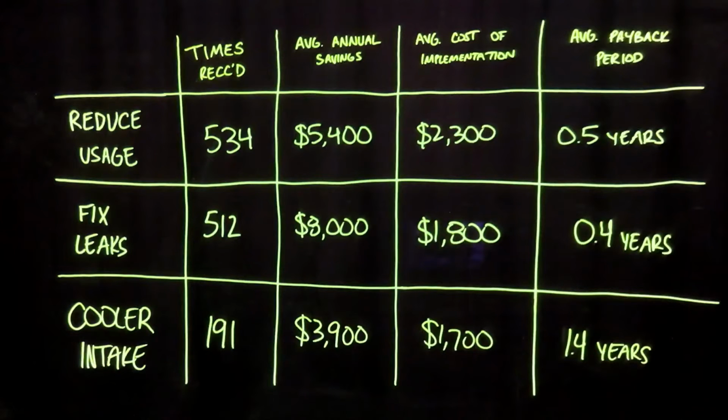When selecting an intake location, it's important to verify air quality by checking that the location of the entry to the inlet pipe is as free as possible from ambient contaminants, such as rain, dirt, and humid discharge from a cooling tower. The Department of Energy suggests reducing the intake temperature by locating the intake filter outside the room or building. If it is outside the building, it's particularly important to take into consideration the ambient conditions.